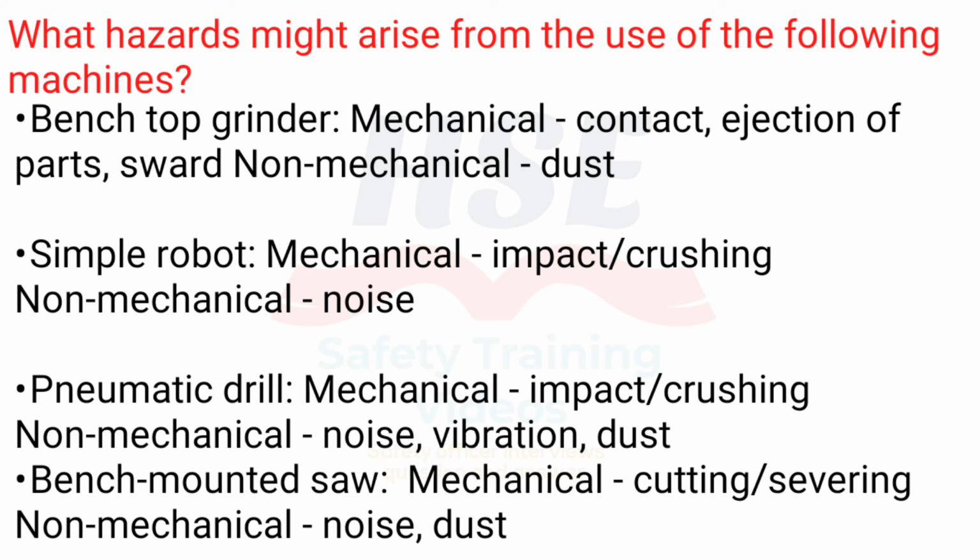Simple robot: mechanical, impact, crushing; non-mechanical, noise. Pneumatic drill: mechanical, impact, crushing; non-mechanical, noise, vibration, dust. Bench-mounted saw: mechanical, cutting, severing; non-mechanical, noise, dust.